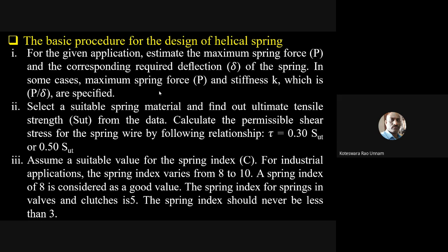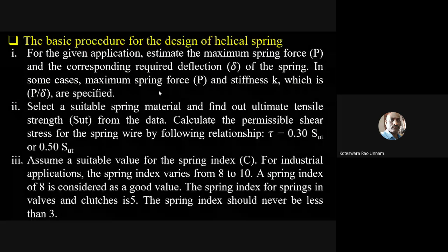But once you have the ultimate tensile strength SUT, then using static failure theories, we are able to find out the allowable shear stress. Here the permissible shear stress for a spring wire is taken as 0.3 times SUT or 0.5 times SUT. For spring materials, generally, if you use the maximum shear stress theory, your SYS is nothing but 0.5 times SY.